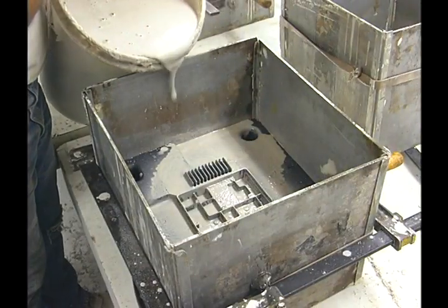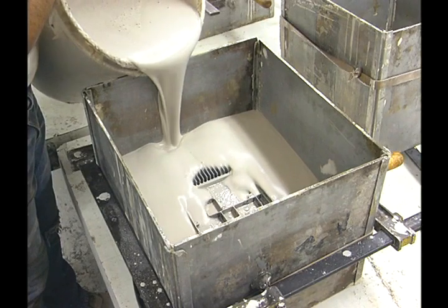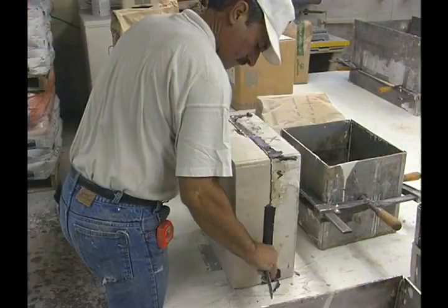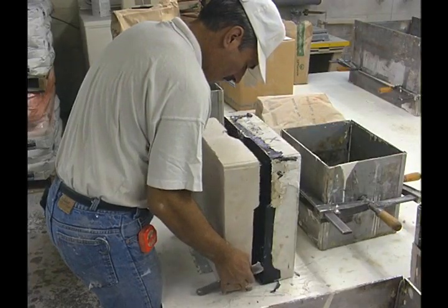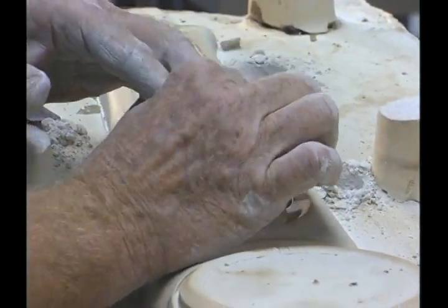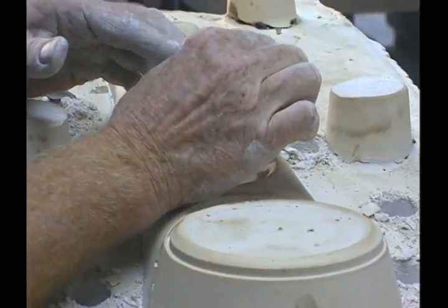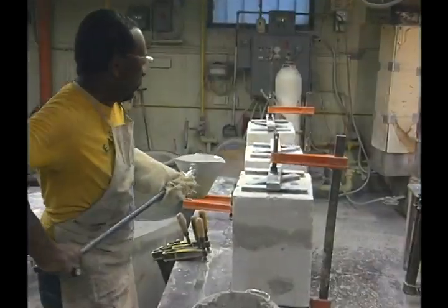The mixture, in slurry form, is poured over the pattern and allowed to set and harden. Once set, the mold is separated from the pattern and baked to remove the moisture. The molds may incorporate metal inserts called chills to speed solidification and enhance the strength of the casting in local regions.